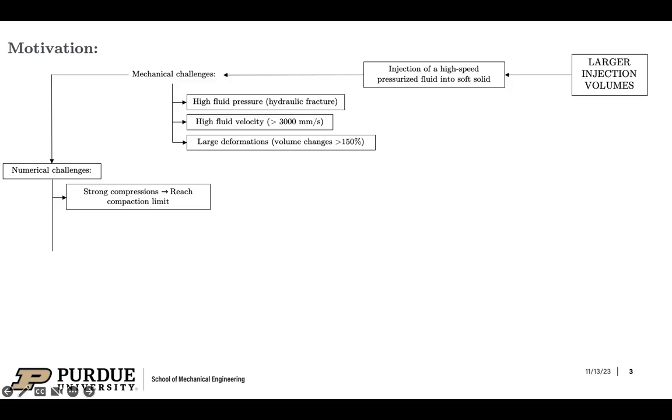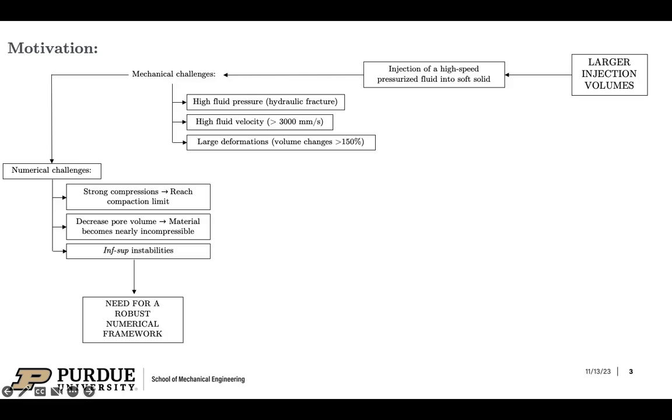From the numerical standpoint, these strong compressions can lead to multiple locking phenomena related to reaching the compaction limit, or to the fact that the tissue exhibits a nearly incompressible constitutive response at the drained limit. Also, we can face the so-called inf-sup instabilities, which arise when the numerical scheme does not fulfill the inf-sup condition. Therefore, we need a robust computational approach capable of handling all these challenges.